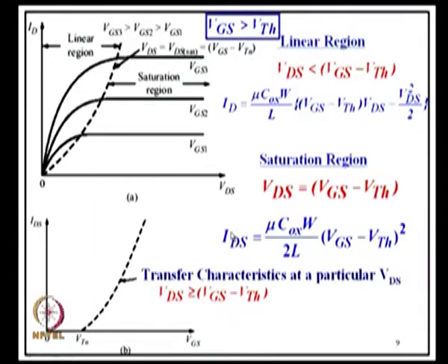Because transconductance defined as delta IDS by delta VGS is proportional to C oxide and W. You would increase W, you get larger current and larger transconductance, but you do not like that. Why do not you like it? Because it occupies a lot of space, width, and it will also give rise to larger capacitance.